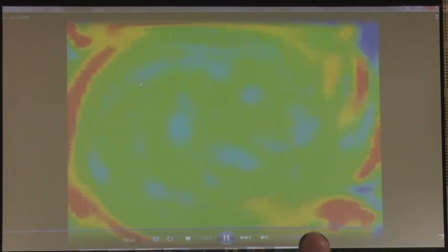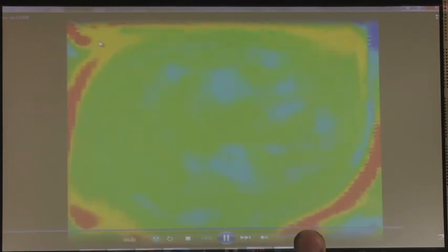At the top you have a wall which is sliding, and then it is entraining the flow by viscous friction, and it generates a big vortex, and inside that big vortex, you see in the corners, you have many small vortices. So again, this is pure DNS at some Reynolds number. The problem is, if you increase the Reynolds number, you will decrease the size of all the small eddies that you see, and you need a more and more refined mesh.